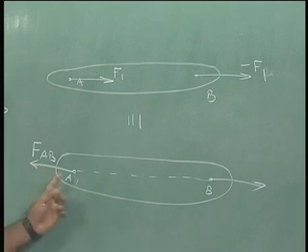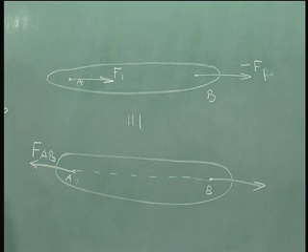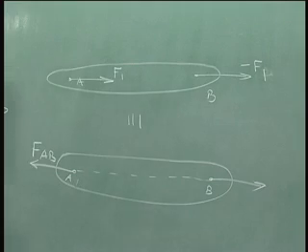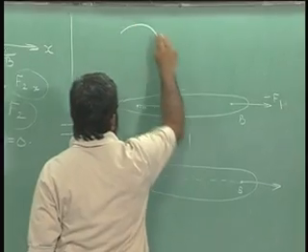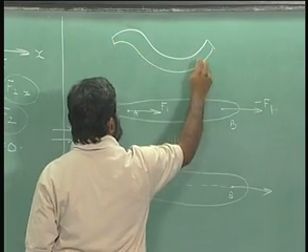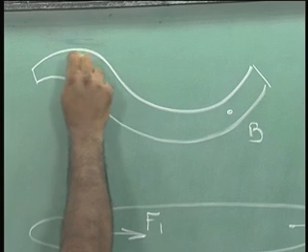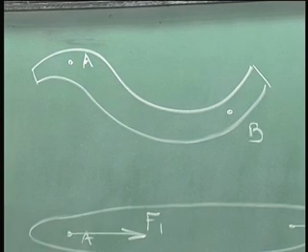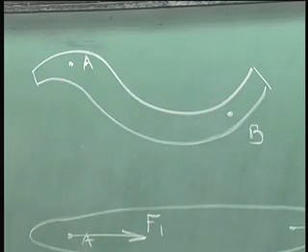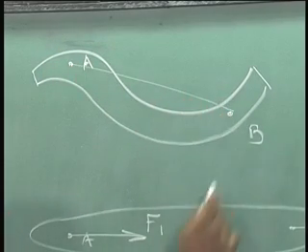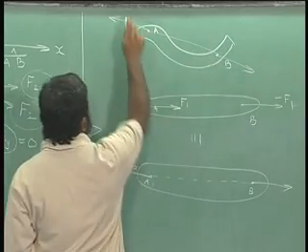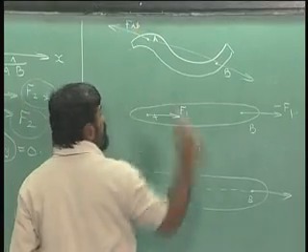Now this body that I am talking about need not be one single straight member like this. Let me draw it over here, I can also have something like this. Let us say this is point B, this is point A. If I know that the forces are acting only at A and B, I can just connect these two and say that the resultant forces on this particular rigid body will be acting along this direction.